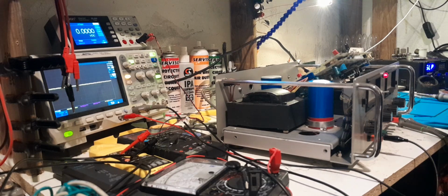Silly move, I guess, because this is such an older design. Everything's designed for older, higher current bipolar technology op amps. So all the bias networking and current considerations and dropper resistors are going to be a lot chunkier than what you're going to find in a power supply these days. And the layout's a bit different too.